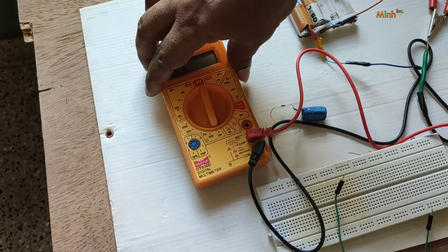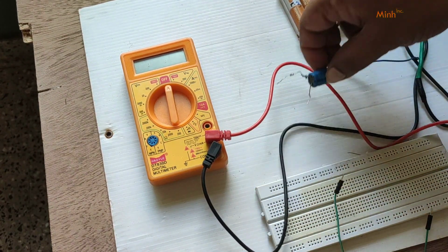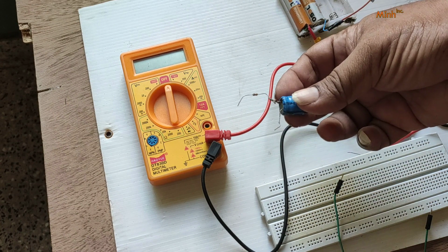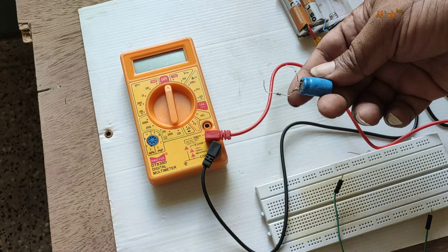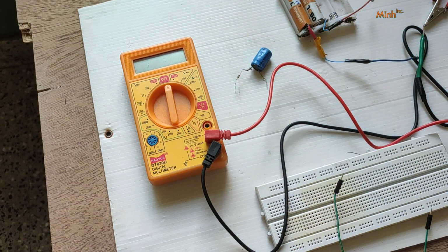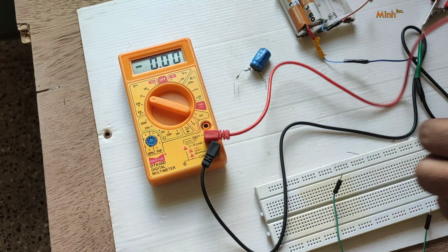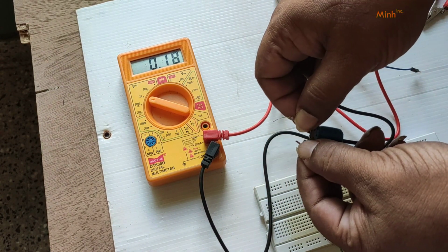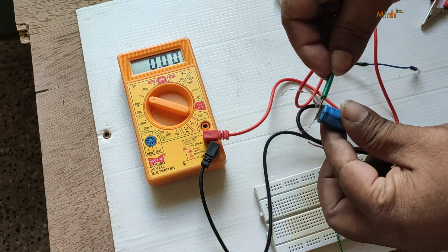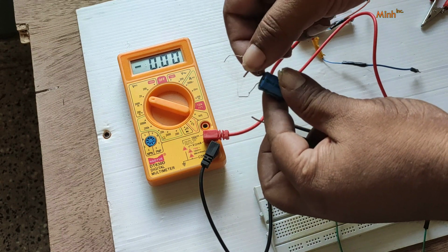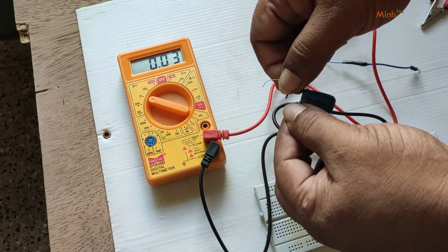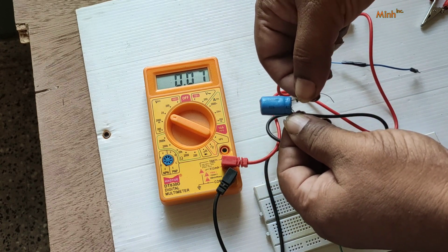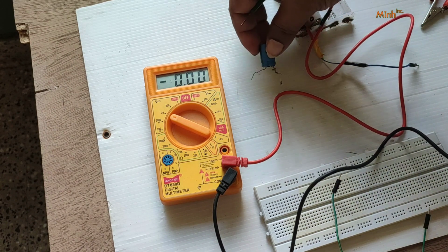We have taken one multimeter, the basic one, and there is one capacitor of 220 microfarad, and a resistance of 56 kilo ohms. So that is the scenario. Now we'll check the voltage across the capacitor, and it should be 0. Okay, there is some voltage, so we'll shunt it and measure again. Okay, now there is no voltage in the capacitor, 0.07 volts, so there is nothing. Okay, so we'll connect it.